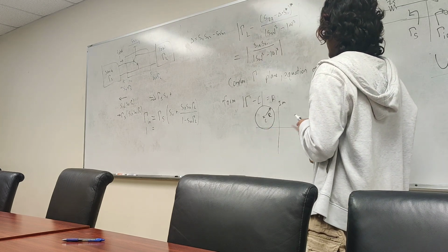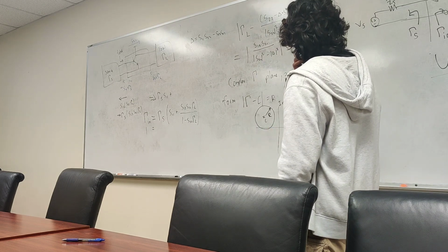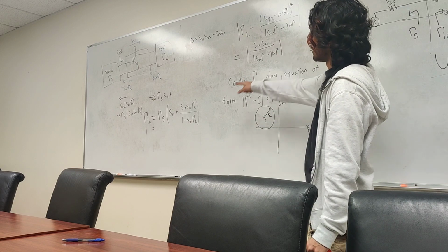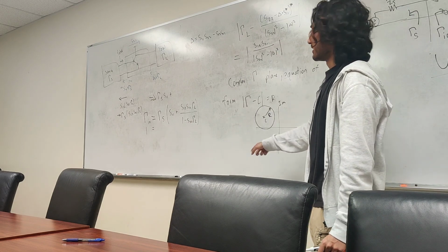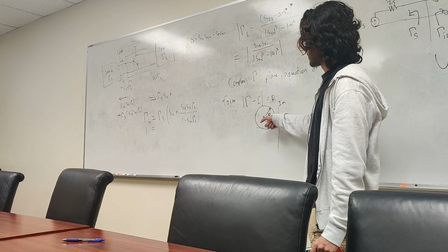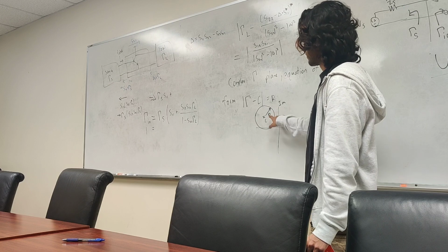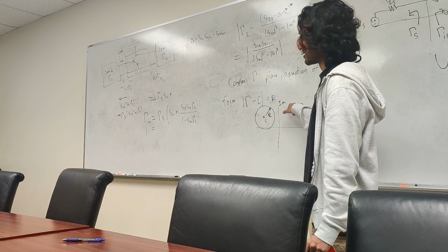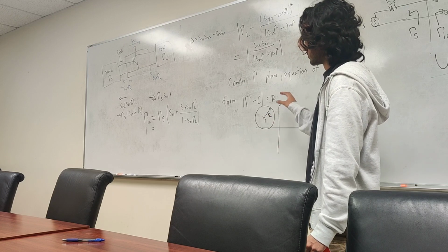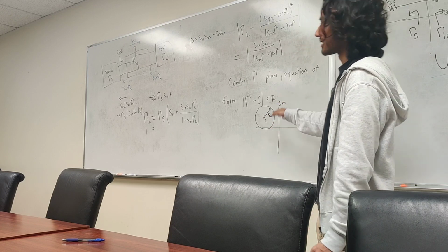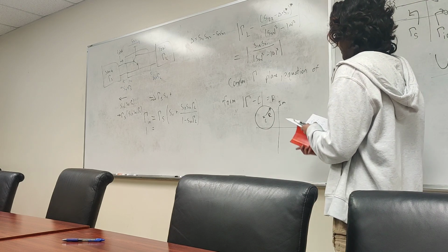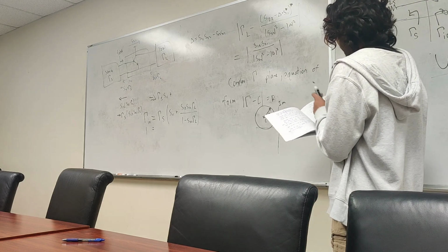Okay. Basically, what this is telling us is that along this circle, no matter where we are, gamma in is 1. This means that we have two distinct regions. This could be a stable region, this could be it, but right now all we know is there are two regions. So we can plot this circle, and then we can figure out which is stable, and we know where we can be to make it unconditionally stable. Okay, so don't be confused by this. I'm skipping a little bit of the derivation there, but hopefully that makes sense.